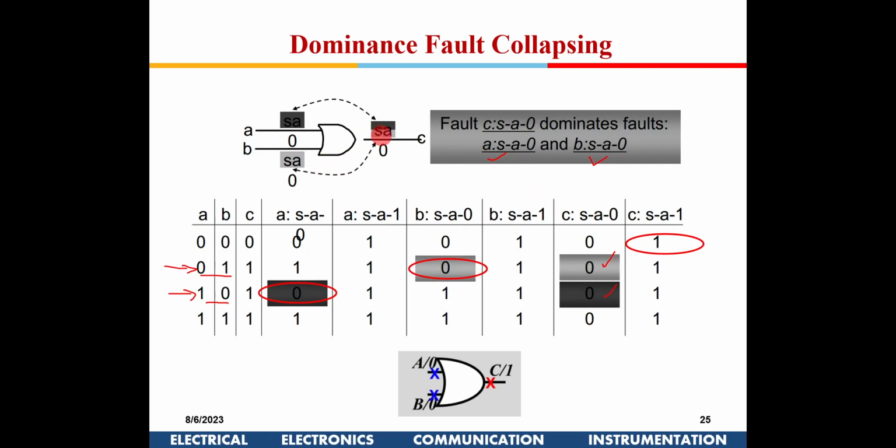So what I can do is, here this stuck at 0, I can either move it to here, or I can move it to here, or I retain this. I can remove this if I am having it stuck at 0. Similarly, finally the OR gate looks like this.